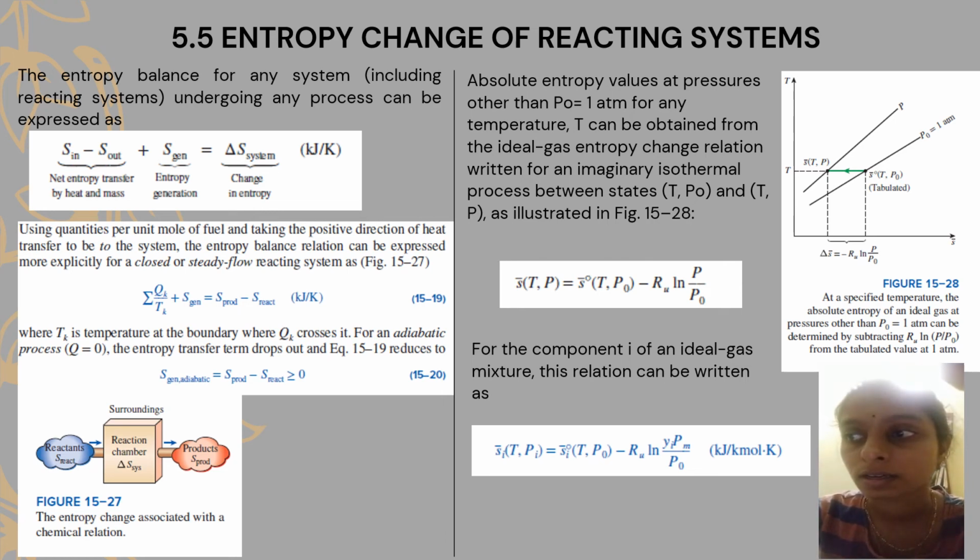And then there is a figure that shows that at a specific temperature, the absolute entropy of an ideal gas at pressures other than 1 atmosphere can be determined by subtracting from the tabulated value at 1 atmosphere.